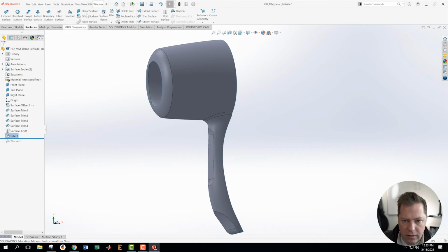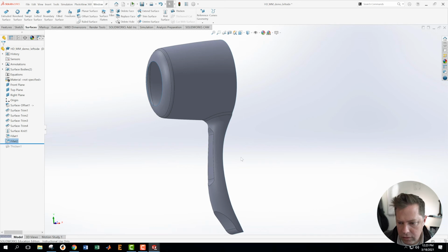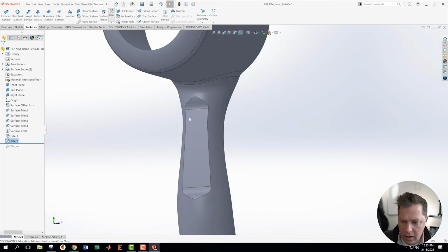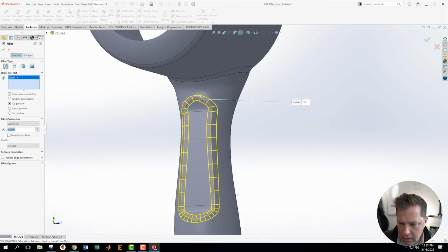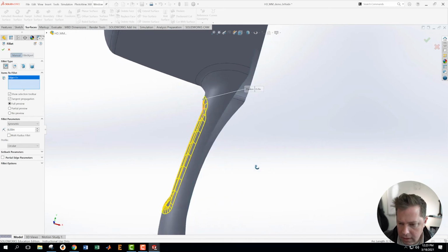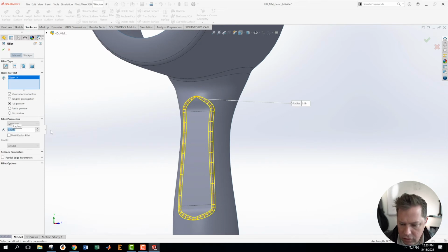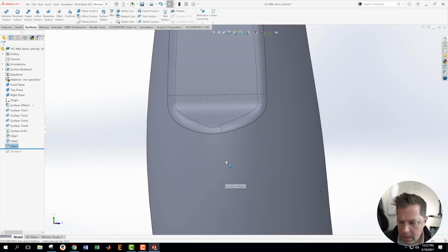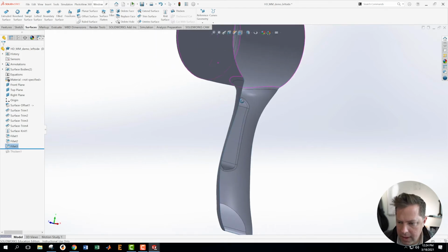Great. Let's actually add the same size fillet right here, 200 thousandths of an inch. Excellent. Let's go get some fillets in on these parts, right in here. Okay, that's pretty giant. I probably don't want it to be that giant. Let's make it 100 thousandths of an inch. Okay, why that line is off from the center, I have no idea. It's a little bit weird. It's probably a problem in there, but I don't have time to think about that.